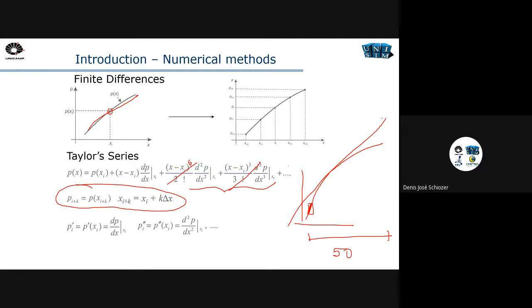So if you are decreasing the size of the blocks, or the size of the discretization we are using, the linear approximation is okay. But if you are increasing the size, you have errors that are related to the size of the block; the errors will be as big as the size of the blocks, or sometimes bigger, okay? So that's why it's very important for us to use smaller blocks. If the blocks are small, the error will be small, and the solutions will be much closer to the real behavior of flow in porous media. If the blocks are big, the errors are big, so we have to consider that in our solution, okay?